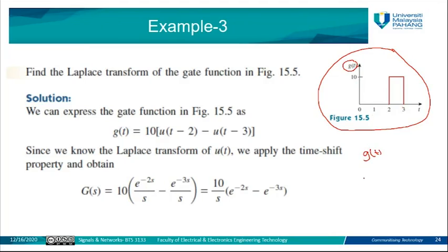After you get g(t), it is easy to find G(s), either by using the integration if it is a simple calculation, or by using the table to find the different parts of this function. So how to write this g(t)? g(t) is actually a unit function. A unit function is like a defined constant number, but it has borders, because the normal u(t) starts from 0 until infinity. It's open from 0 to infinity and gives you the value of 1. If we have 10u(t), it gives you the value of 10, but also from 0 to infinity. But here it is limited to this part.